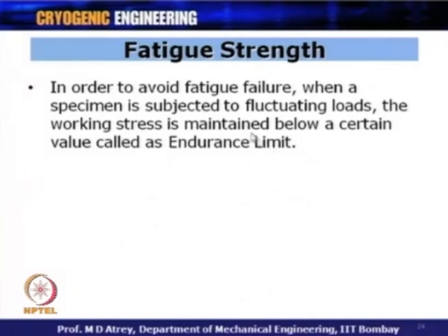So, if I want to worry about a failure which I know is going to happen due to fatigue, what I should worry about is not the fatigue strength but the endurance limit. If I keep the stress generated below the endurance limit, then in principle this material should never fail, and therefore the endurance limit of a material is very important. We should know the endurance limit of a material which is going to be subjected to fatigue loading, and I should ensure that the stresses generated are less than this endurance limit.